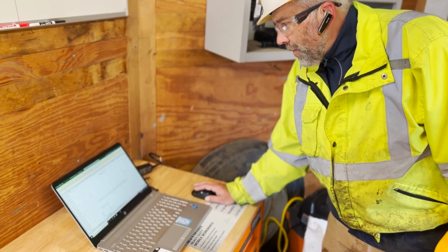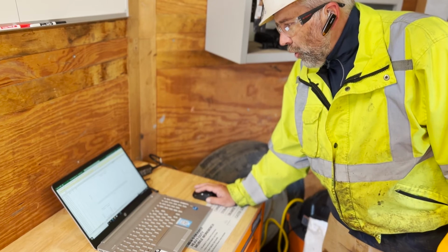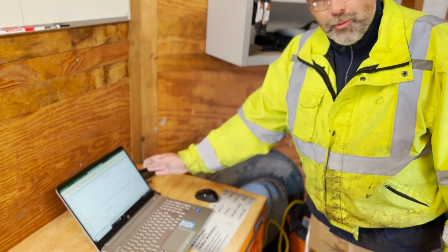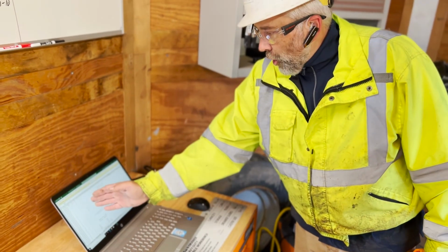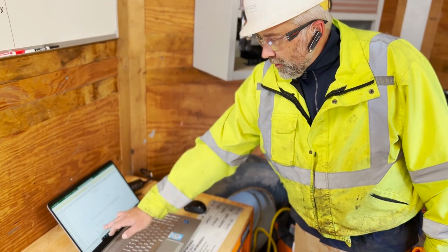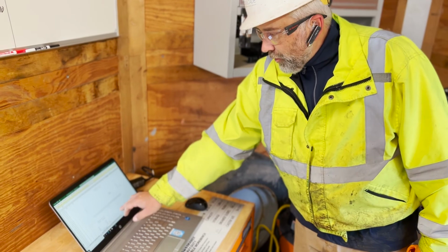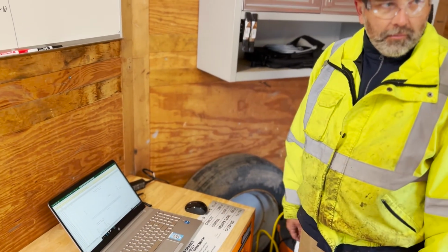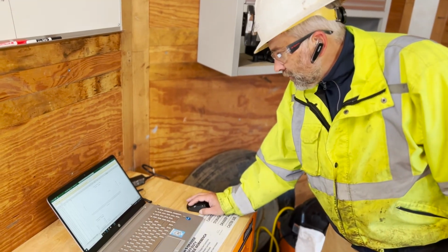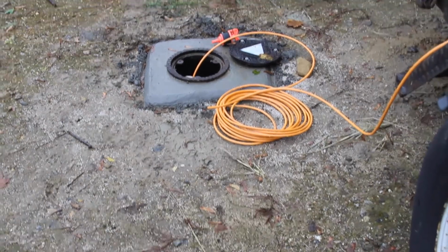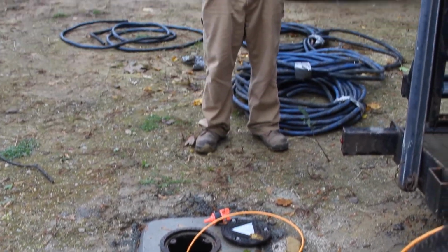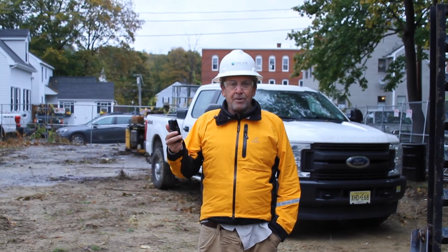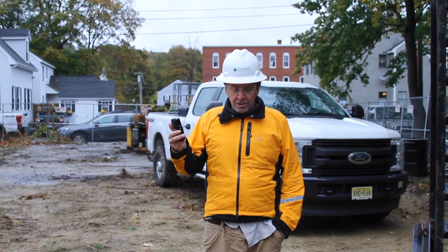And really, to accomplish that, it's very important to understand pressure and flow in these flow paths to get that distribution in contact. Another bit of data that the unit collects that we don't have displayed here yet is the level sensors that we put into adjacent monitoring wells. We can monitor up to 3 wells at a time for groundwater elevation during injections to make sure we're not overmounding a particular injection area.